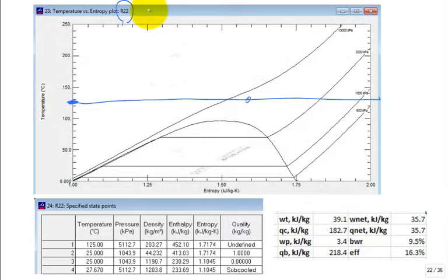I can stop it here. I can stop it here. I can stop it here. Where would you stop it? A, B, or C? Why B? Because when I do the isentropic expansion, it gets into the sweet spot there. Here, it would be A. It's too high. And over here, well, it's too low a quality. Here it's too superheated. Okay.